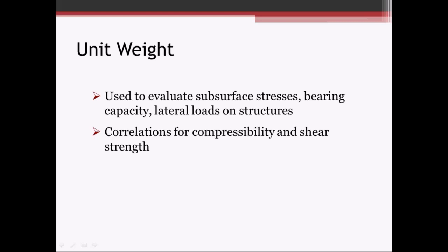Okay, moving on to unit weight. The unit weight test is used to evaluate subsurface stresses, bearing capacity, as well as lateral soil loads on structures. It's applicable to soils that retain their shape. In the lab, we're measuring the weight of the intact sample per the volume of the sample that's being measured. And there are several correlations for compressibility and shear strength using unit weight.